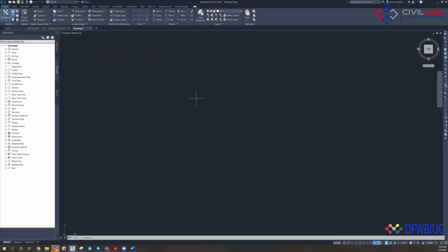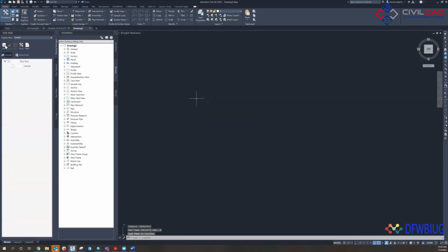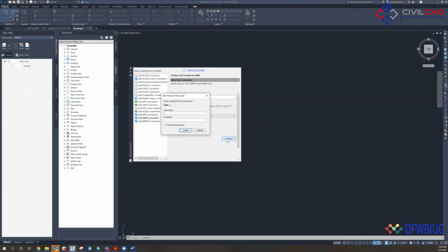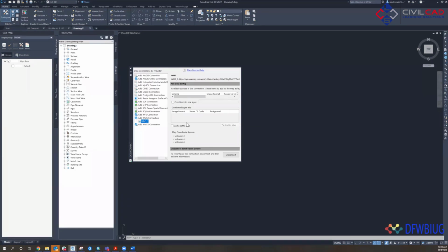Let's see my Civil 3D window. We're going to want to go to the map task pane, and make sure it's turned on. In here, navigate to data, connect to data. Down here, add WMS connection. I copied the link from the Nearmap map browser, so all of our customers get access to the API keys within there. We'll just hit connect. It'll ask you to log in. You don't have to. Yep. That's the step I always do when I first started: I'll try to log into Nearmap.